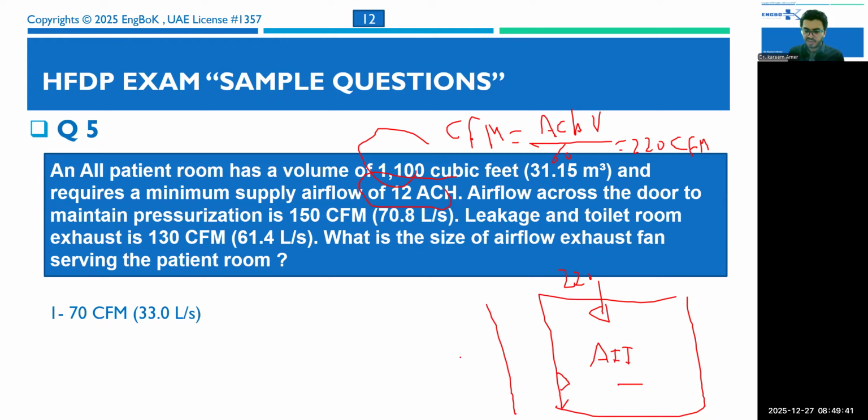The room is negative pressure, so the corridor should be positive relative to it, because, as we said, AII has infectious or contagious disease from the patients. So the airflow should be from the corridor to the room. So undercuts are permissible here for the healthcare facility, to allow 150 CFM to pass.